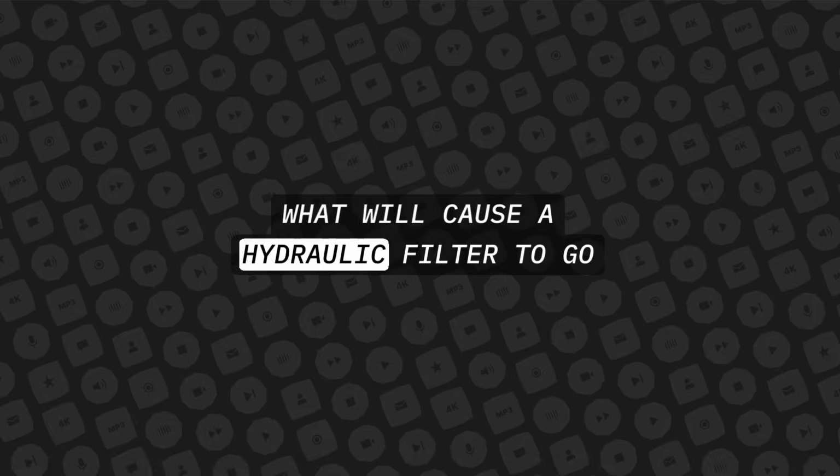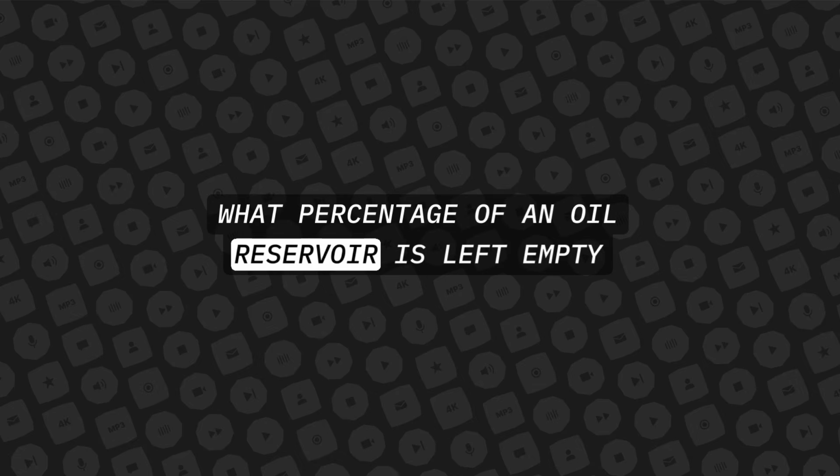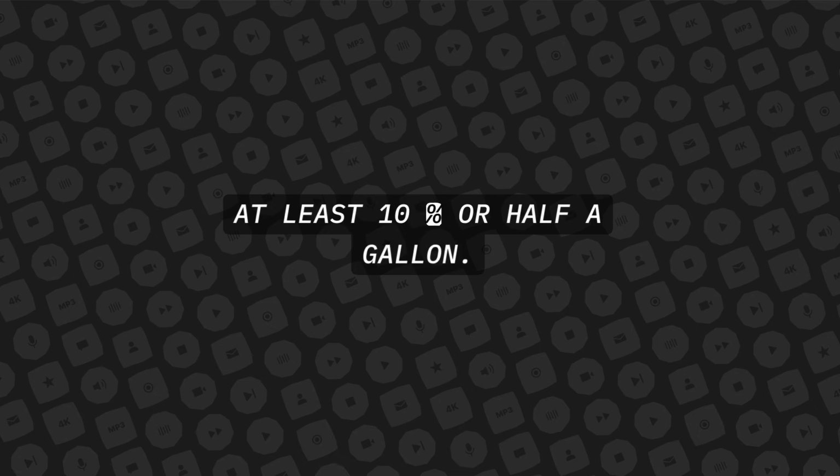What would cause a hydraulic filter to go into full bypass mode, allowing unfiltered fluid into the system? A clogged filter. What percentage of an oil reservoir is left empty for oil expansion? At least 10% or half a gallon.